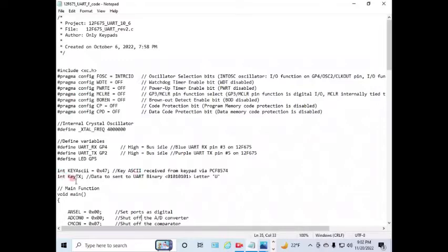And then this other variable, key TX, all I'm going to be doing is transferring this hex value to this variable, because my programming down the road may require that I don't change this key Ascii value at a certain point in time while maybe another key is coming in. So I want to just transfer this into here, and then at that point I'll transfer from the key Ascii to the key TX. You'll see how that works when we get down a little bit further.